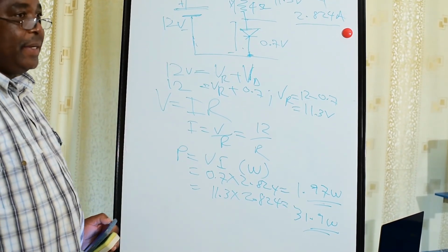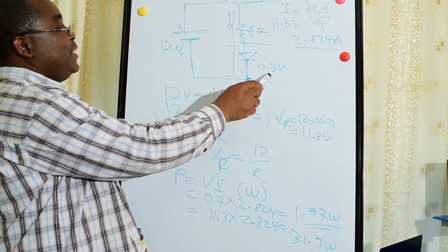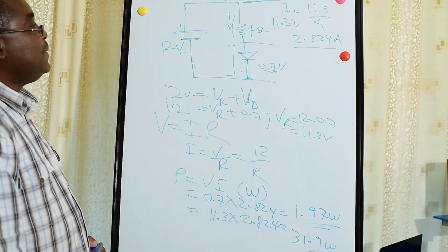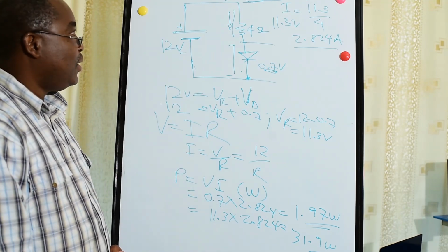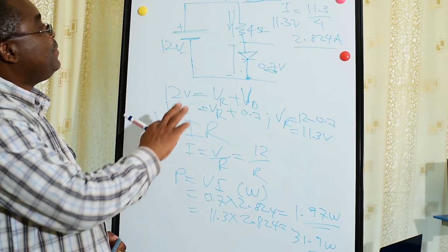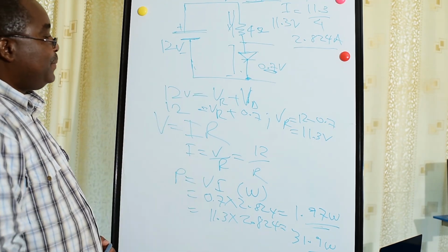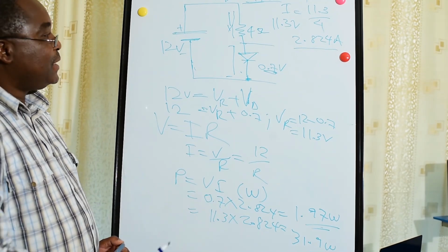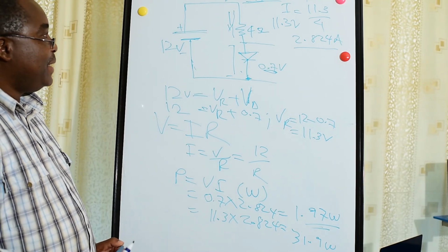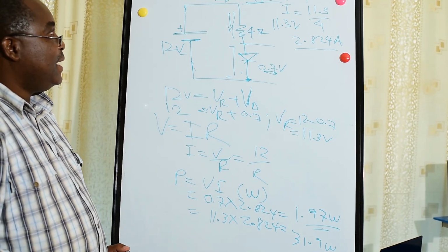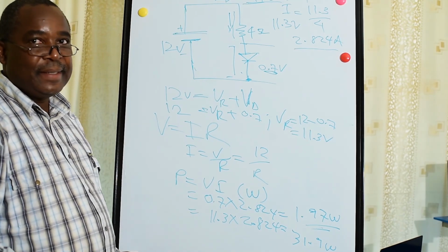So in practice, the diode will conduct when the voltage is 0.7, and it will be from high potential to a lower potential. So this is a simple circuit, which is a resistor and a diode. We come in lesson 3 to a bit complex circuit, which will have many resistors and diodes, and we'll see how we can see the relation between current, voltage, and resistance.